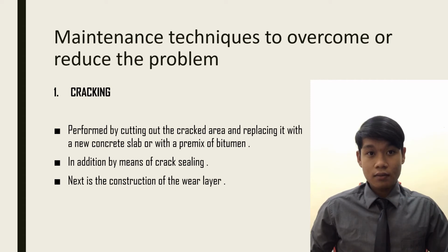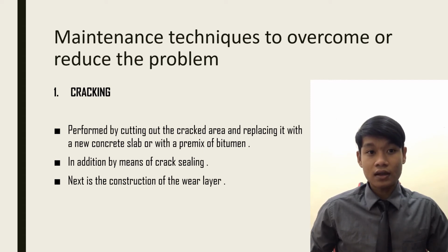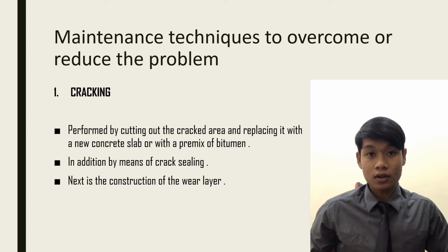Okay, next, maintenance techniques to overcome or reduce the problem of cracking. Okay, first, perform by cutting out the crack area and replacing it with a new concrete slab or with a premix of bitumen. Okay, in addition, by crack sealing. Okay, next is the construction of the wear layer. Okay, next I give to the next presenter to continue this presentation.